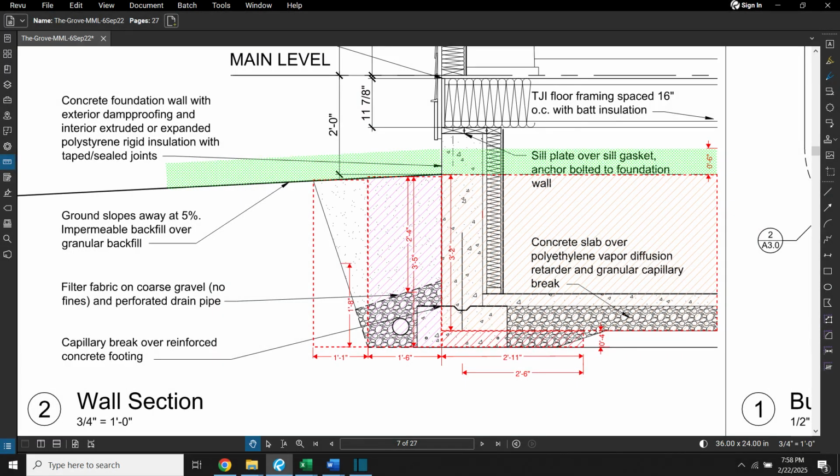Unlike the area and volume measurements for clearing and topsoil removal, measuring cut and fill quantities requires referencing the wall section on page 7. I have highlighted key dimensions in the wall section to help quantify the earthwork materials. The green hashed section represents the removed topsoil, which we already measured as 6 inches deep. The next step is to measure the cut quantity for the crawl space.